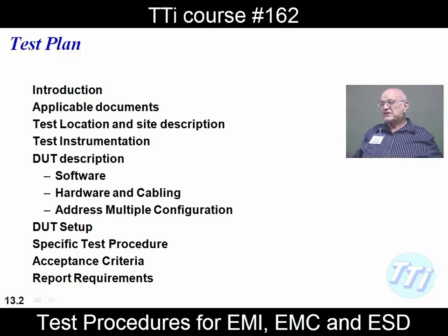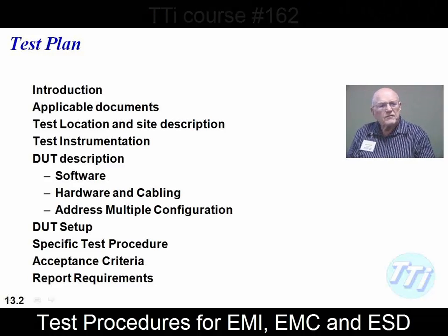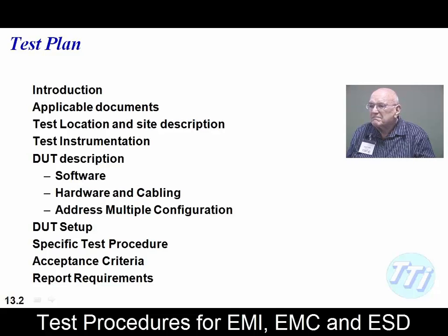You maybe met them before and that kind of thing. And then the actual test instrumentation that is going to be used. Spectrum analyzer. Is that enough? What do you think? No. I don't know that you would necessarily need to specify a model or a brand, because you may be going to a test house that already has a certain spectrum analyzer set up, but you're probably providing, hey, we need 30 kilohertz up to 30 megahertz. Okay, a general specification. Right.